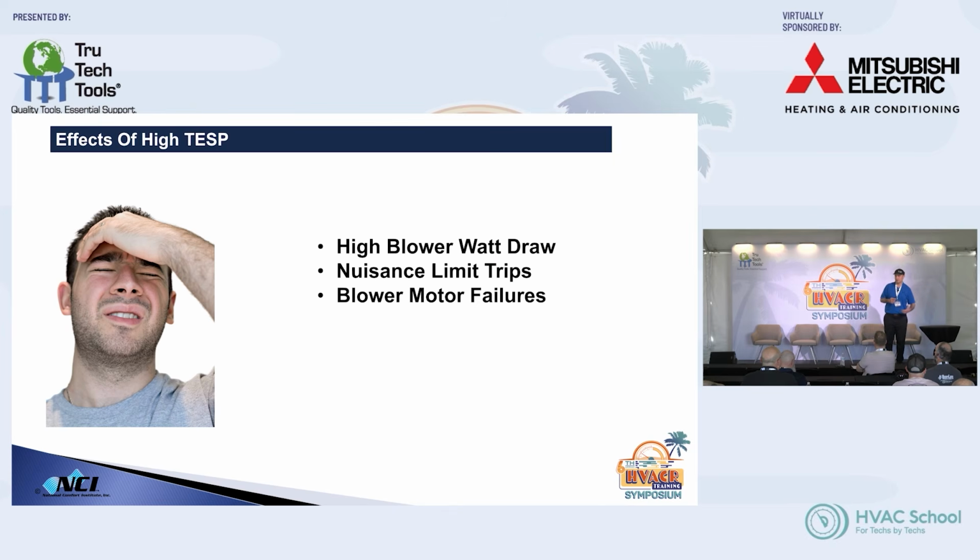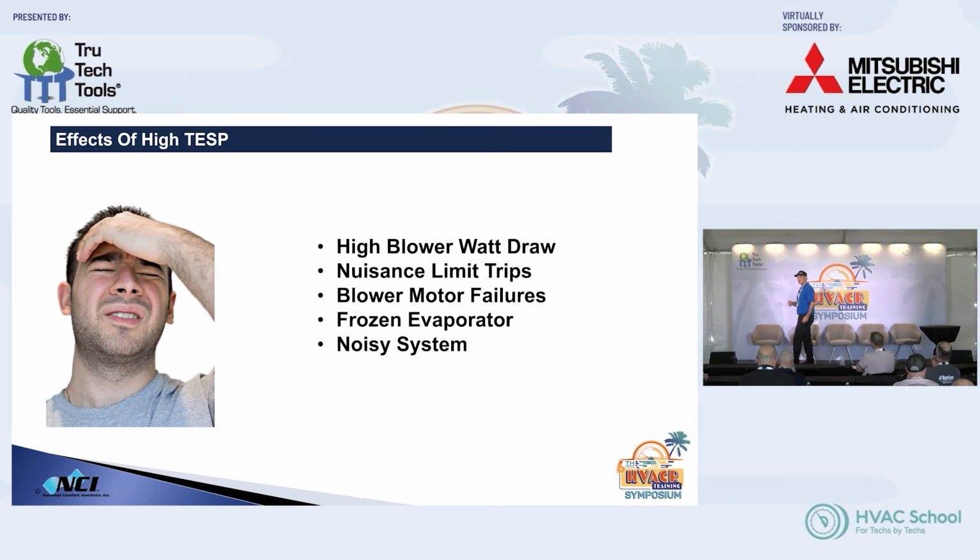Blower motor failures, that's another huge thing. I know with ECM, when you have high static pressure, they don't work as well, they don't last as long with high static pressure as they did in the past. Frozen evaporator coils, noisy. I had this in my first house where when the furnace or AC would kick on, you would have to turn up the volume on the TV when you're sitting there watching TV at night. So if you wanted to get through a movie, you had to turn off the heater air, right?